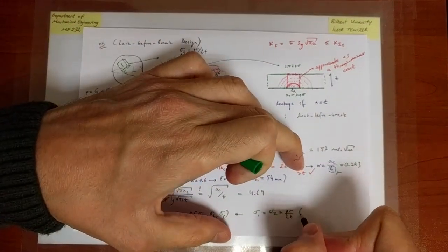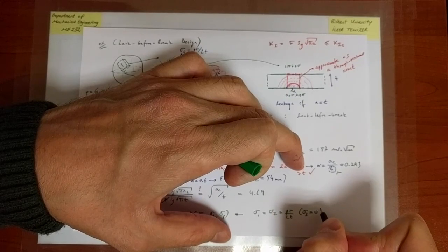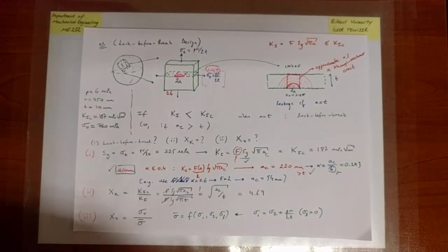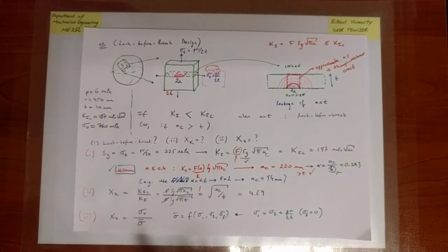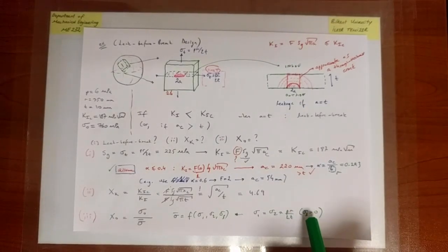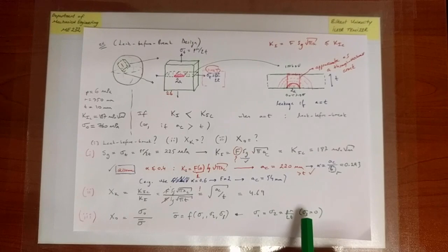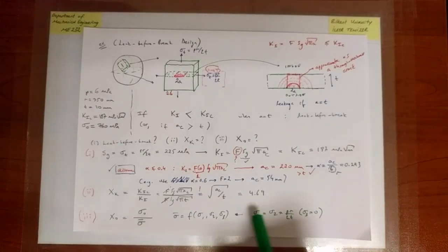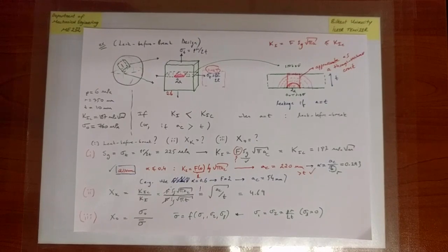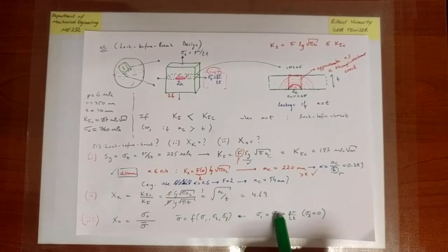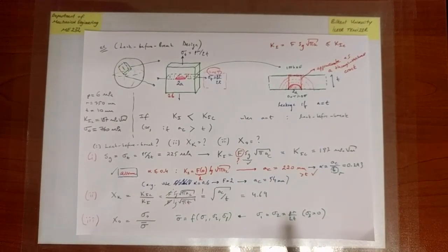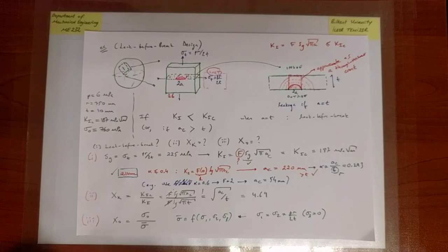And I will assume, as I have done previously as well, that sigma 3, which is the normal stress in the radial direction, is omittable because it's proportional to simply P. It's minus 6 MPa, 6 MPa in absolute value only. So compared to a value of 225, it's very small. So we have a state of really plane stress. And we know that for a state of plane stress with equal principal stresses in the remaining two directions, it really doesn't matter whether I use the von Mises or the Tresca criterion. Both of them will predict exactly the same equivalent stress.